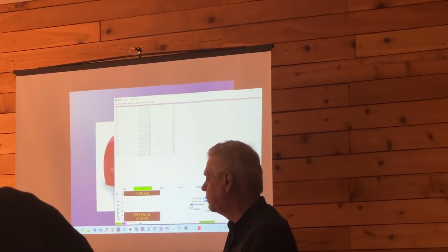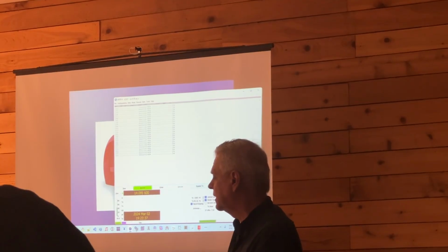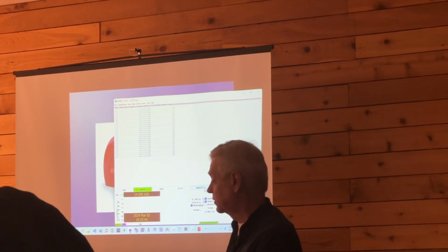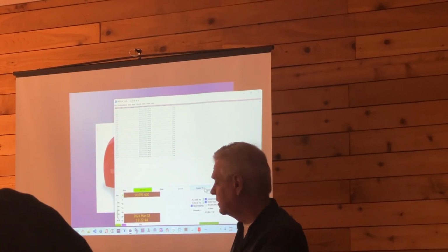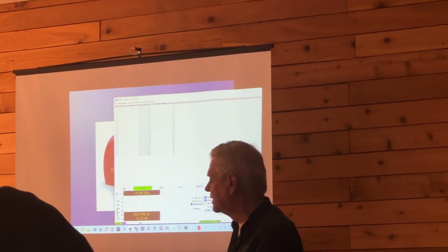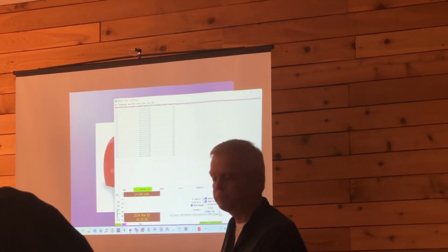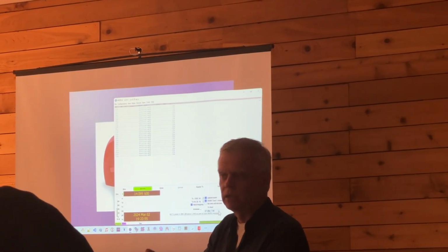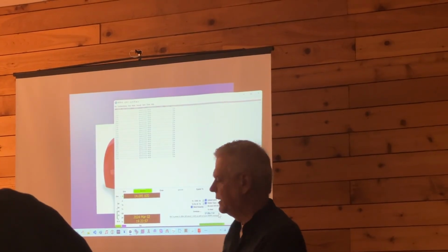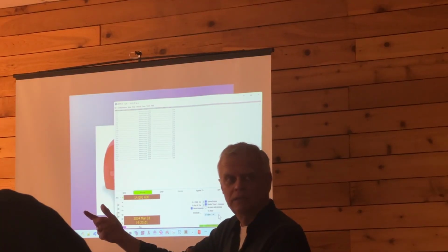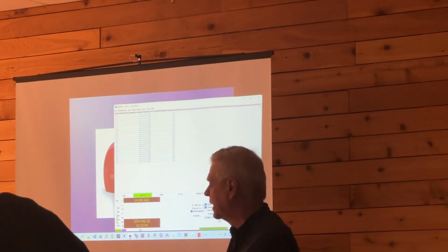The last thing in passing right here is these buttons: your tune button, enable, which will get the program to actually transmit, and this selection right here, which is what power you're transmitting. Whisper requires you to enter the power that you're transmitting in your transceiver. It doesn't read that from your transceiver, so you have to tell it, so that you can report to WSPRnet what actual power you're using.